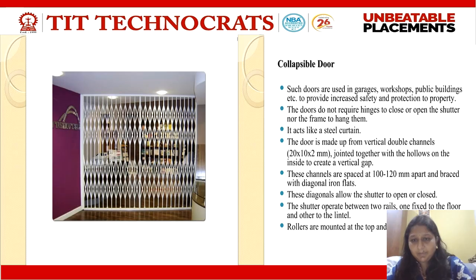They are generally made up of double channels. Their channels are spaced approximately 100 to 120 mm apart from each other. The inclined members here, wherever I use inclined metallic members, are called what? Braces. So this type of door is called a collapsible type of door. The rollers are mounted at the bottom and the top, through which the door can be moved.